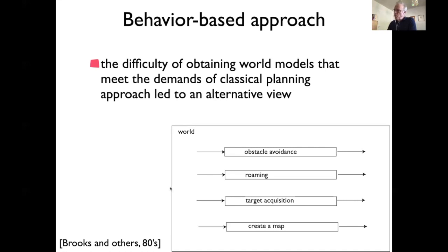In this view, you would build the robot from a bunch of different behaviors, and each behavior has its own special purpose sensory input and acts on motors. They would be quite restrained with respect to how they interact. In some proposals, they can only activate each other. Sometimes they can what is called subsume, that is, provide the input to another module or get the input from another behavior, sorry. This avoids having the same architecture problem again, just between these objects.